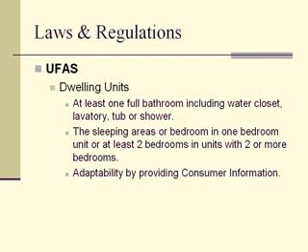Okay, so now for the specific dwelling units, what we will see is that at least one full bathroom, including a lavatory, a toilet, a water closet, tub, or shower must be accessible. And basically that means providing one water closet with all the grab bars with the clear floor spaces, the lavatory mounted at the proper heights with clear floor spaces,